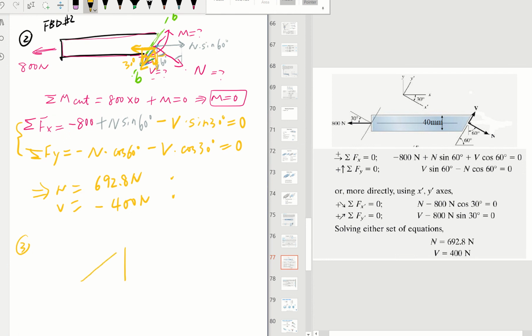If I cut straight or I cut slanted, which one will have more surface? This is a 2D view, because we're going to consider the depth going inside. Of course, the slanted cut is going to have more surface area. But how much more? We're going to use trigonometry to figure it out. This is 40, and this angle is 60, so we can figure out this hypotenuse length. The hypotenuse length will be 40 divided by sine 60, right?